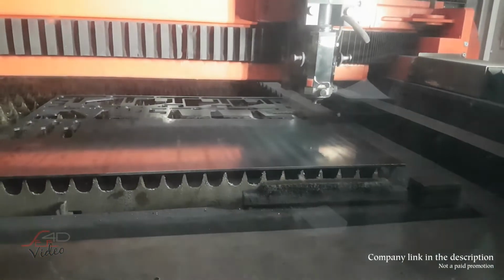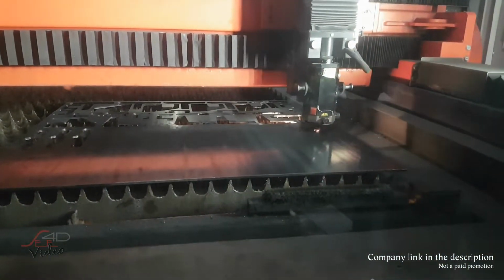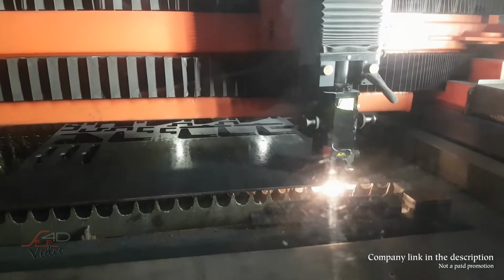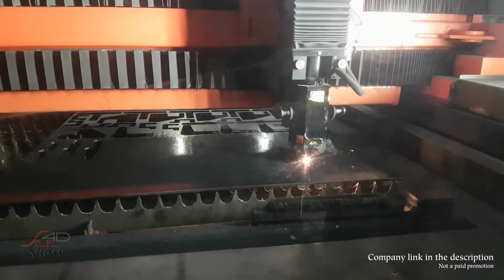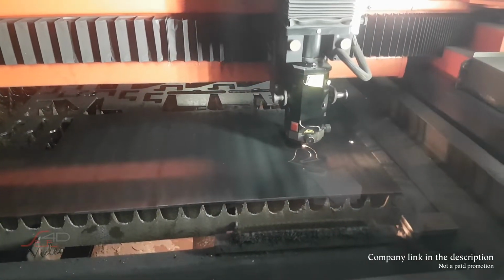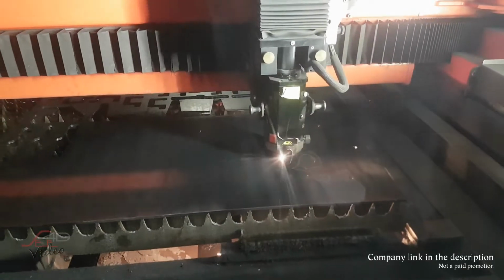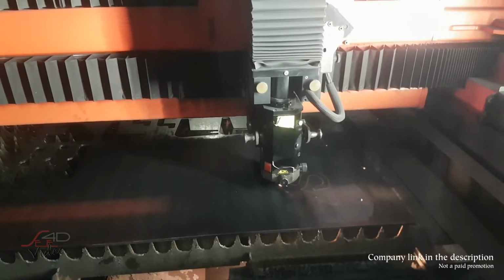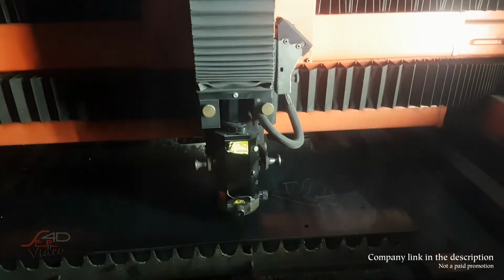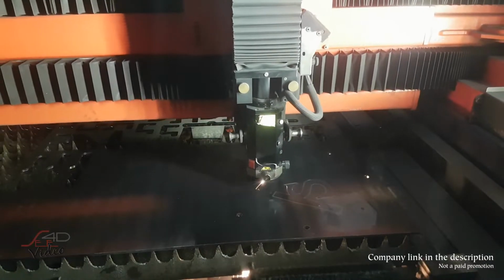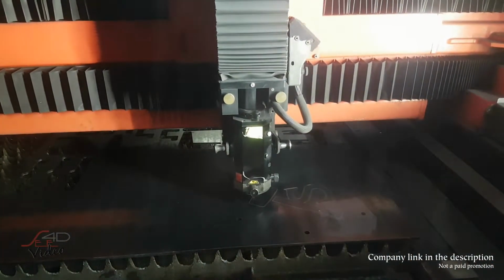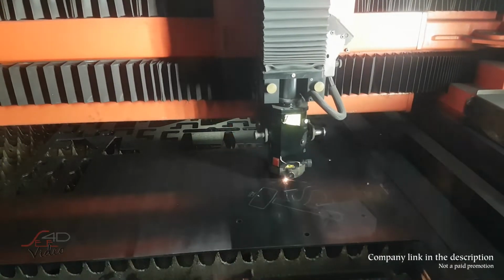What's important here, the laser is cutting metal really precisely. The edges are crisp, sharp, and if you're not careful, you can cut yourself. Therefore, in the last part of the video, I'm showing you the deburring process. I deburred the holes and the borders, since I had experience cutting myself on the laser cut borders. They are so clean and crisp, and also after the cutout, the metal plate is not hot. It's lukewarm, and you can handle the material without any gloves right out of the laser.